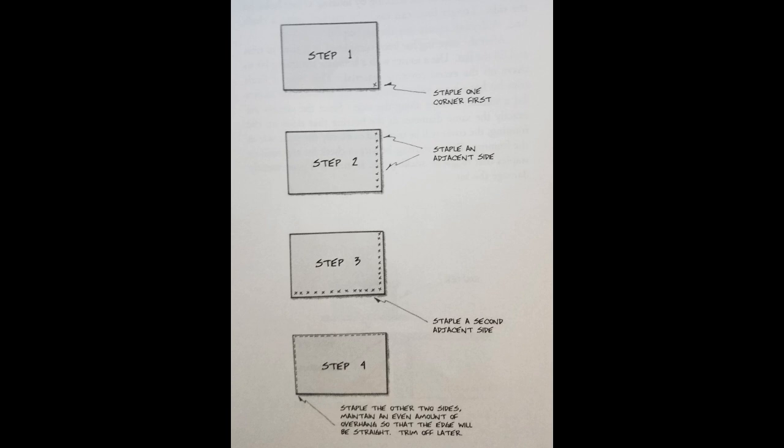When you're attaching the face, it is typically advised to again start in one corner like you would do the actual framing of the project. And from there, you work the short side first. As you go along, you line up the edge of the Luan with the edge of the frame. This ensures that it stays nice and flat and flush for when you actually stand it upright, so that there isn't anything causing it to bend or be pushed in one direction or the other.